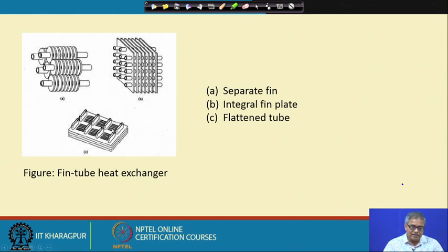Surface modification, in the sense maybe there are some holes or serrations or louvers. This will give some sort of agitation or good mixing of the gas stream which is passing over these fins. So many things we have done. First thing, you see how this concept of compactness has increased.